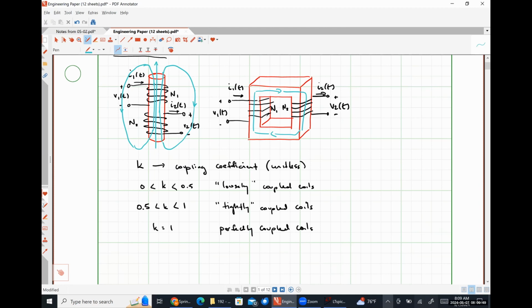Effectively, because the material is conductive, we can induce what are called eddy currents. Eddy currents develop a magnetic field that is opposing the changing flux that's passing through. And so by laminating the core or cutting it into very thin strips, separated by very thin insulating materials, we can make sure that the eddy currents that are induced in the core are very, very small and therefore don't oppose the flux, so that our losses are minimized.